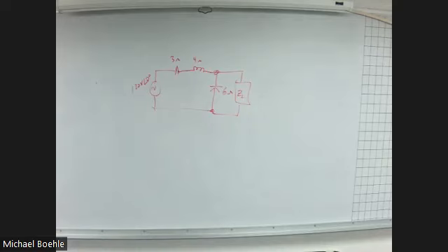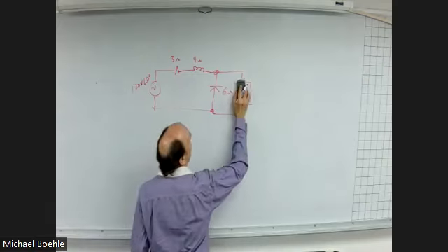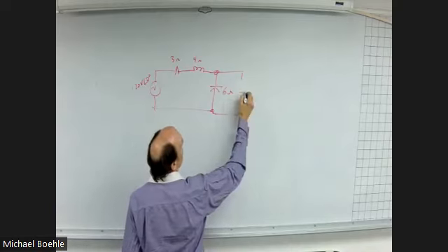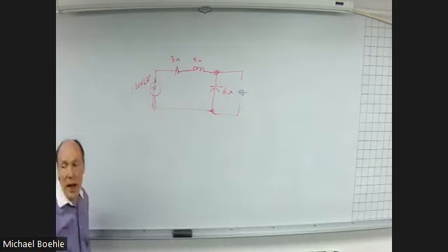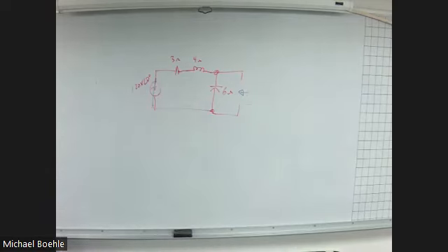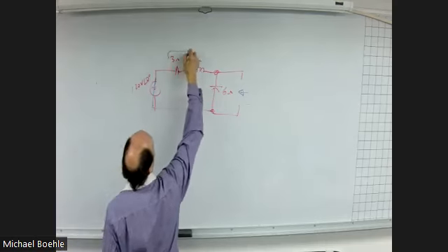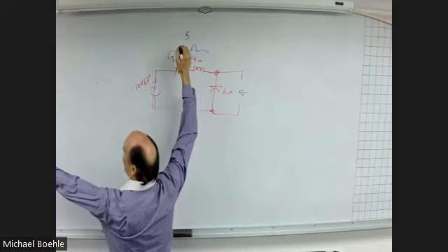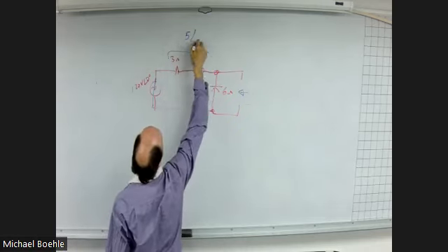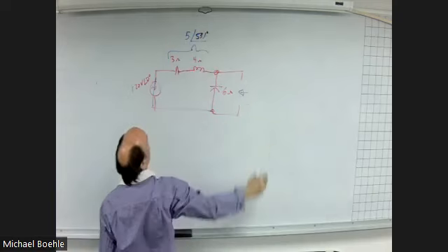Yep. Okay. So for this one, first thing we want to know is what is the load impedance to get maximum power transfer? Well, to do that, we need to know the Thevenin impedance. So to get that, remove the load, look back in here, replace that with a short. What do we have? Well, we have these two in series. So those two in series are, from our numbers over here, 5 at 53.1 degrees.